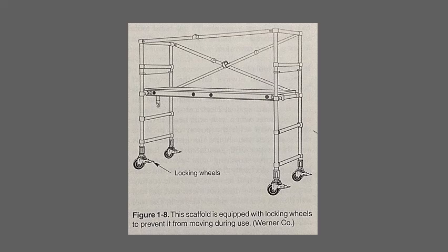If you can, tie the scaffold off as well, especially if it is several platforms high. Always use a ladder to get onto the scaffold. Never climb the braces of the scaffold.